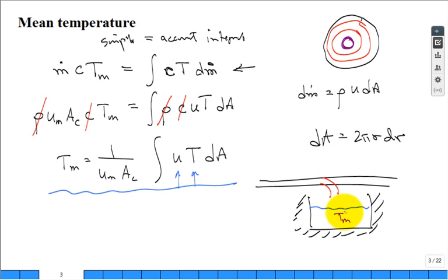Again, take the thought experiment and for 1 second or 1 minute or whatever, some unit of time, divert all the flow at some cross-section in the pipe into a well-insulated container. Let it sit, let it mix, get one average temperature for that mixture, and there you go.